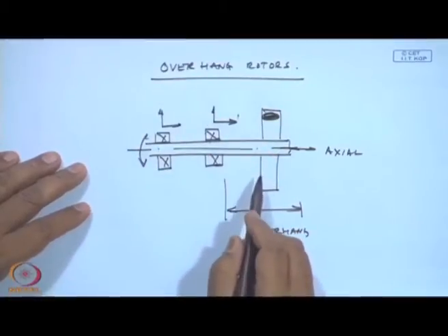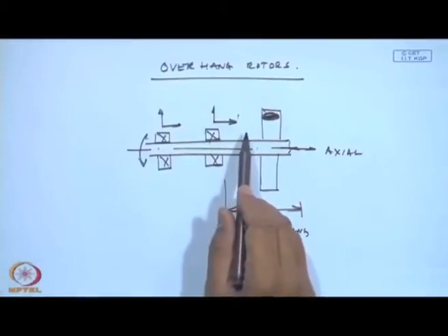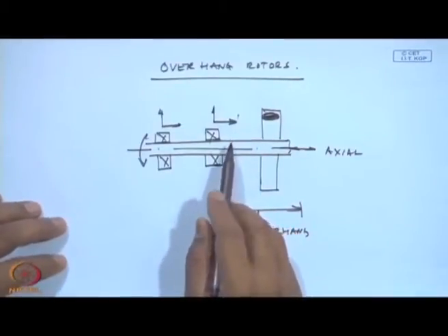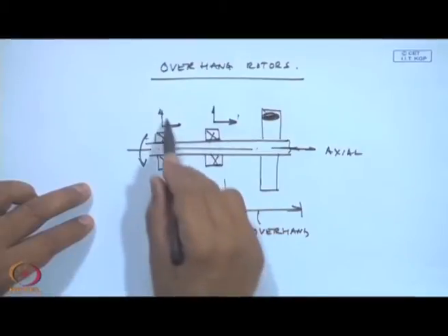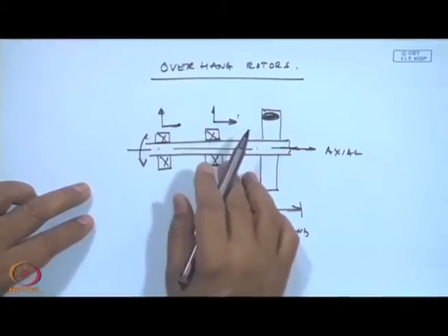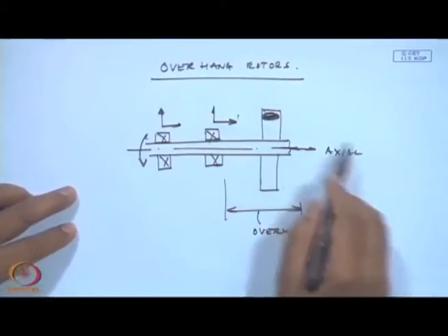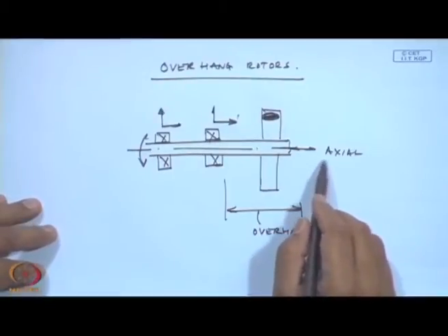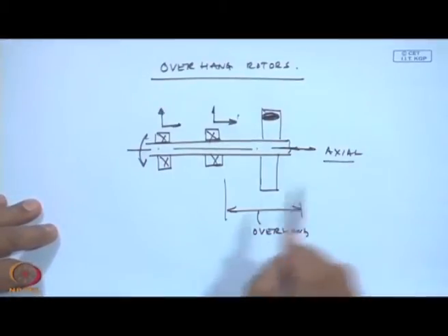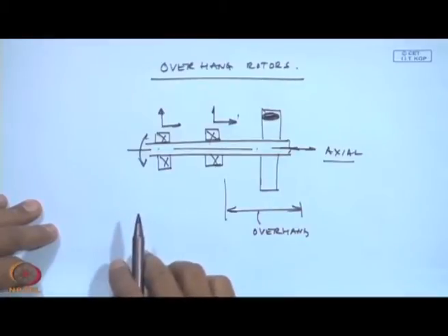Though the axial vibration may be unsteady, and the axial phase between these two may be a little unstable, they may not be stable. And this is again an example wherein unbalance on the overhang rotor can be detected.